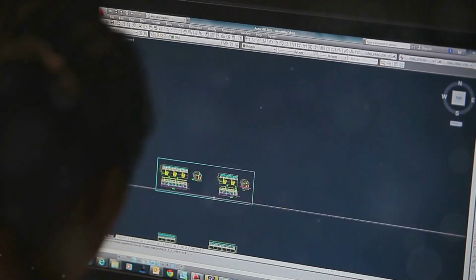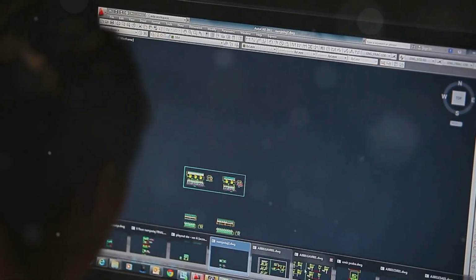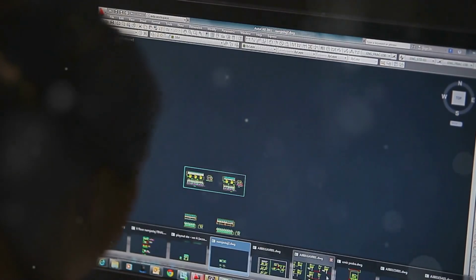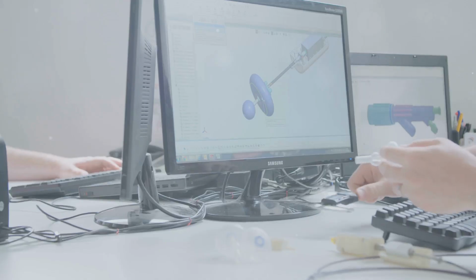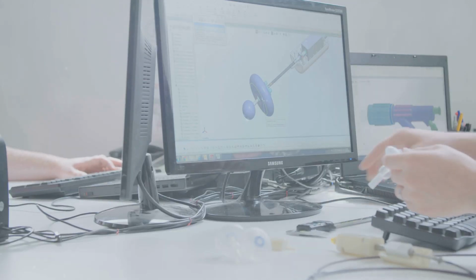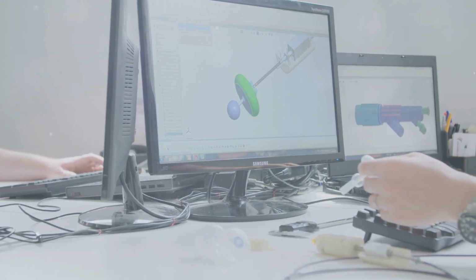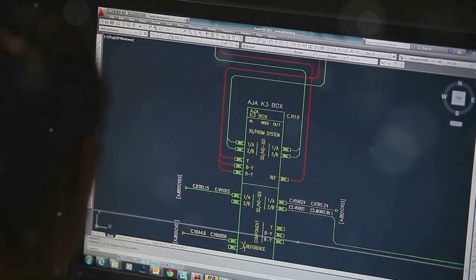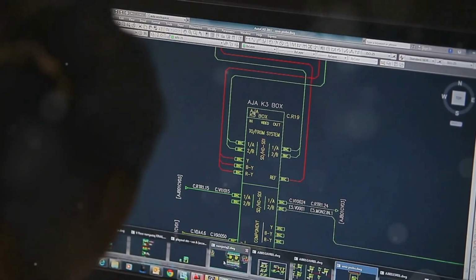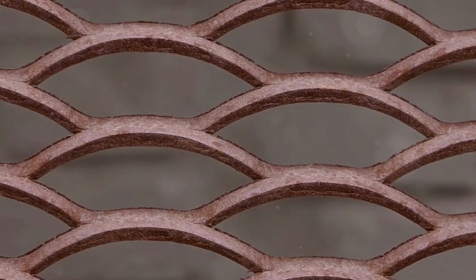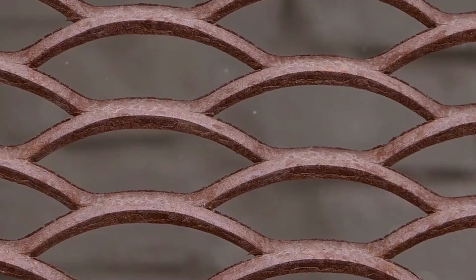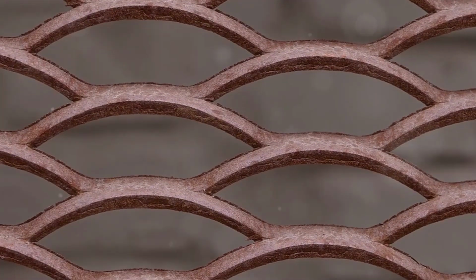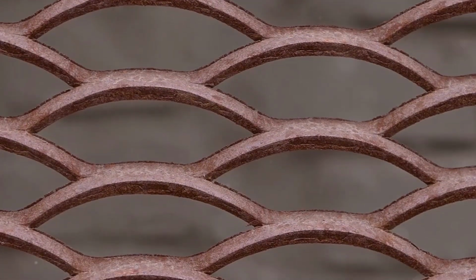Let's delve into the steps involved in setting up a co-simulation FSI analysis in ANSYS Workbench. This workflow is particularly well suited for problems with significant fluid structure interaction. First, define the geometry by creating or importing the geometry of the structure and the fluid domain. Next, generate the mesh, a discretization of the geometry into smaller elements which are used to solve the governing equations.